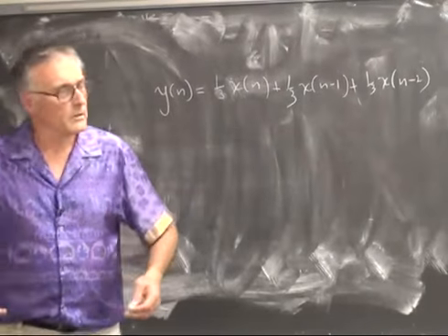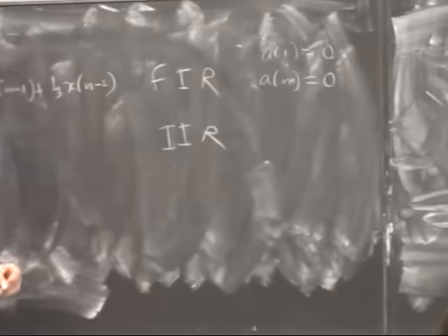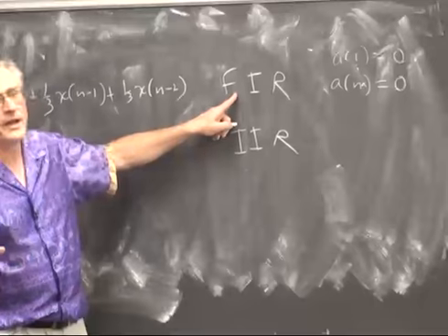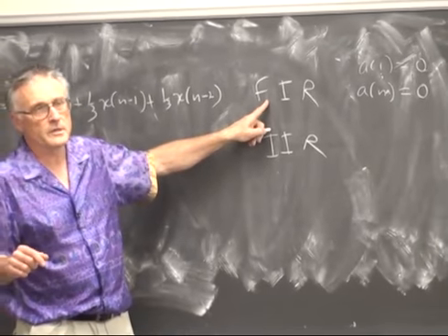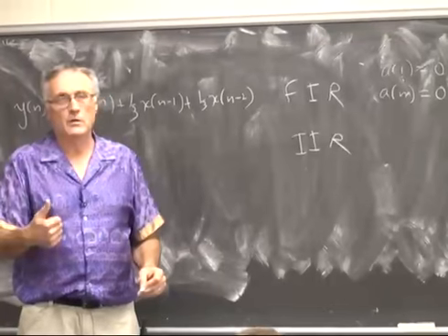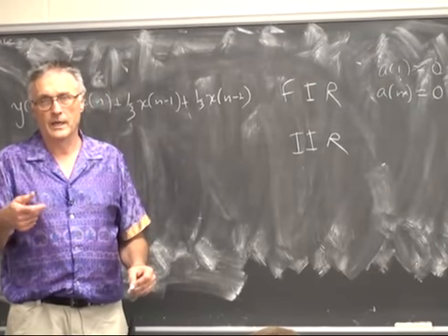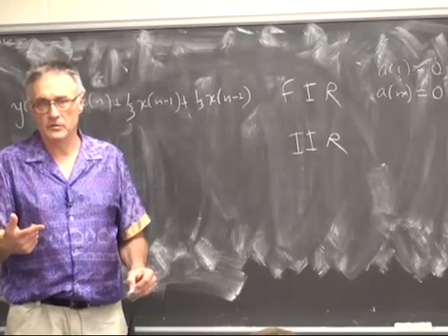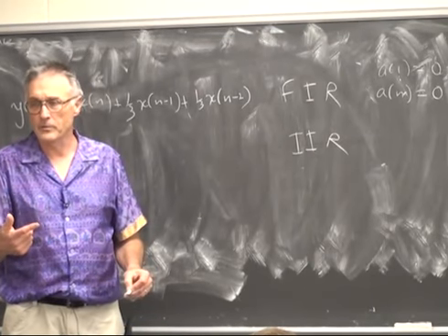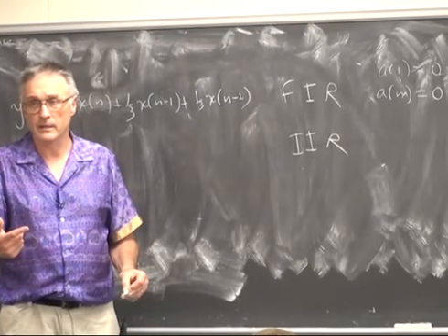In general, finite impulse response filters, now I'm not going to prove this, I'm just going to state it. We can talk about it more if you want. In general, finite impulse response filters give you more controllable phase shift. There is a set of design tools which are completely arbitrary and allow you to have any shape filter that you want. The so-called Parks-McClellan algorithm.